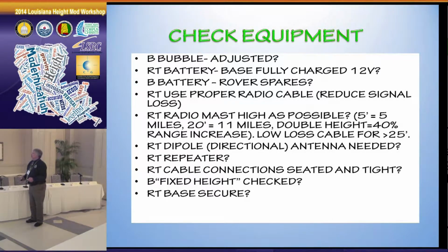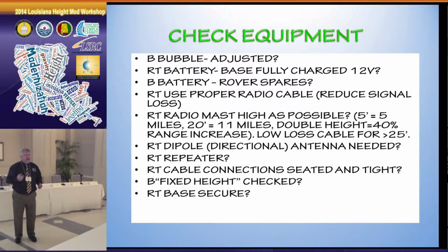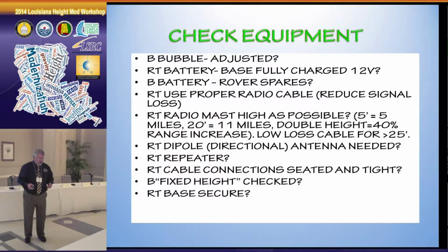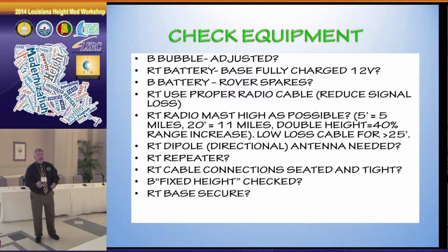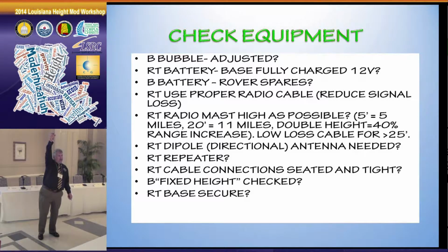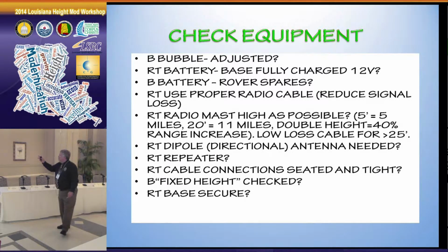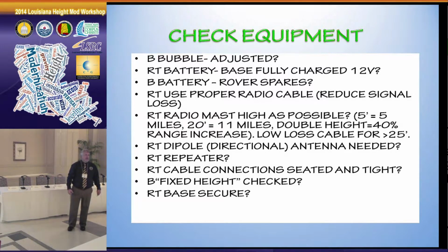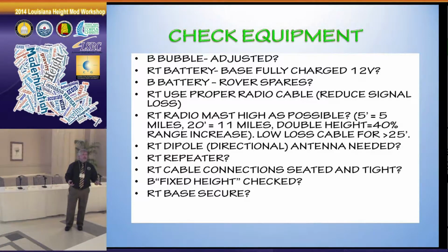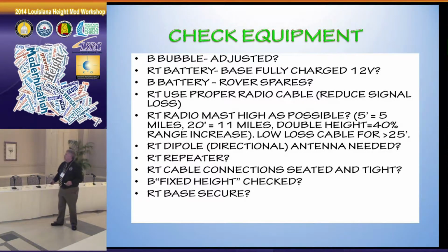Here's the thing that a lot of people don't understand, or don't use. I actually saw this at Trimble Dimensions a number of years ago. There's a guy that did a session on this for single base positioning. If you're using a UHF radio, if you elevate your radio broadcast antenna, you're extending your range. He said if you double your height, you can get 40% more range for your real time. Sometimes that's important, at least it was for me.